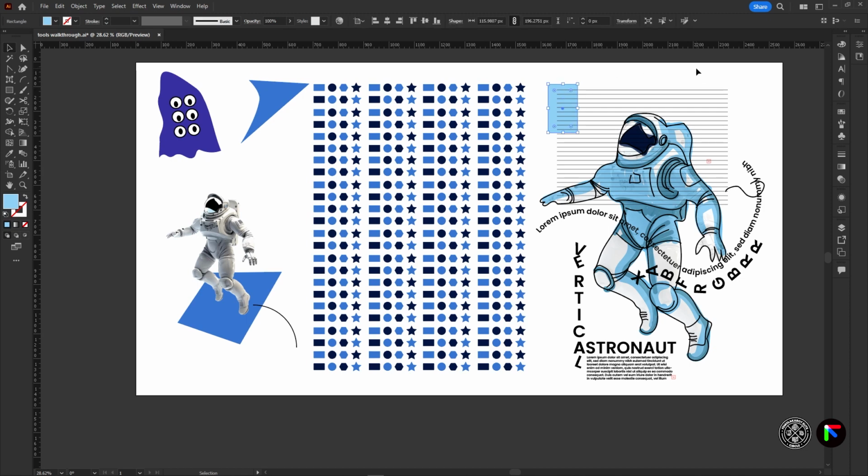But one thing to know about the object tools is that you can also manipulate their corners by either chamfering them or making them rounded. For example, say this little guy right here. You can click and drag in, and then you have a capsule, and then click and drag out to a certain extent to have a rounded rectangle.